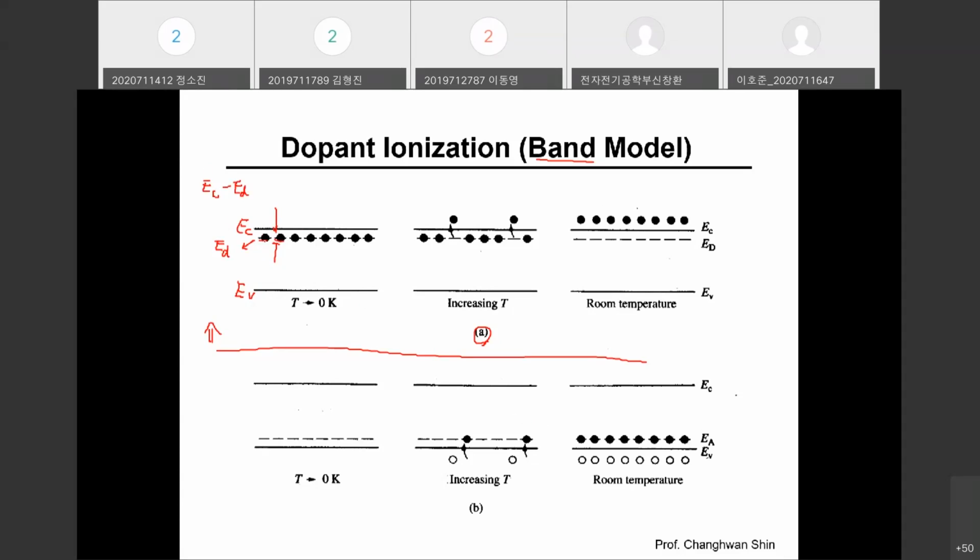In this case, the type of dopant is donors, and since it is not room temperature but 0 Kelvin, everything is frozen out. So the dopant atom is well bonded to the silicon atom. The situation is like this: given a silicon crystalline material, suppose that a silicon atom is replaced with phosphorus, an atom from column 5 in the periodic table, so the total number of outermost electrons is 5. The fifth electron is still well bonded to the phosphorus atom at 0 Kelvin.